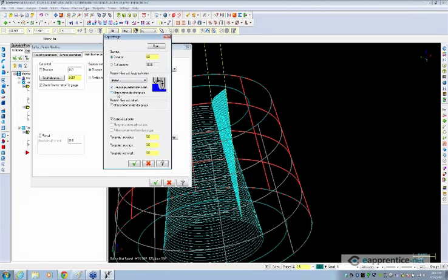In order to be able to uncheck that checkbox, you have to either use direct or you have to use broken. So if I set this to smooth, well, actually smooth will let me, but follow surfaces has to have check gap motion for gouge set. So follow surfaces we can't do. Smooth in this case doesn't make any sense, because this would be if we were going off the edge of a surface, and in this case we're not. We want to stay touching the surface the whole time. So what we'll use here is direct.